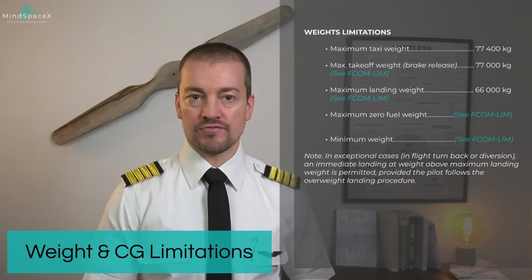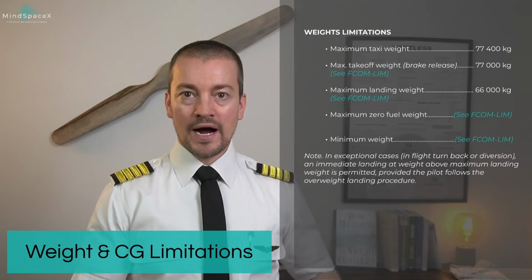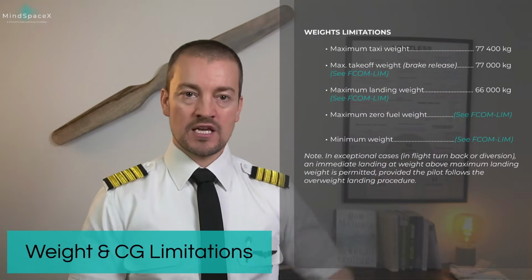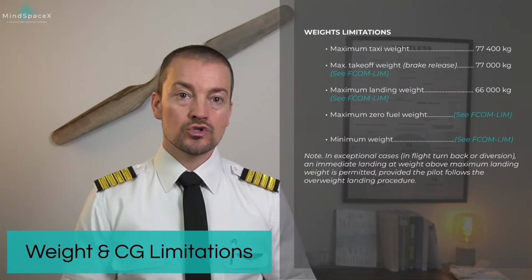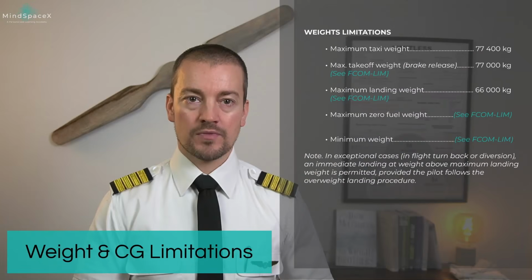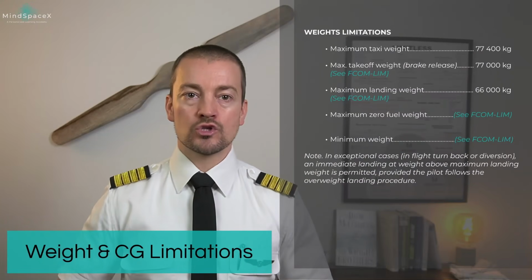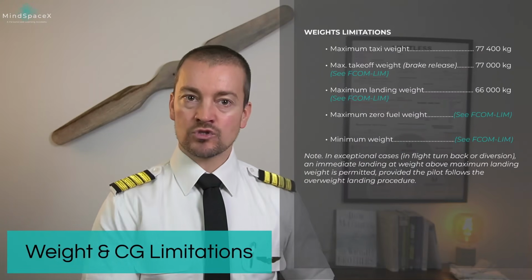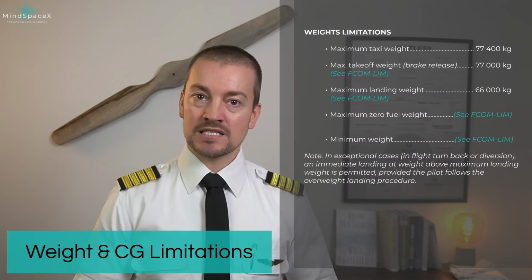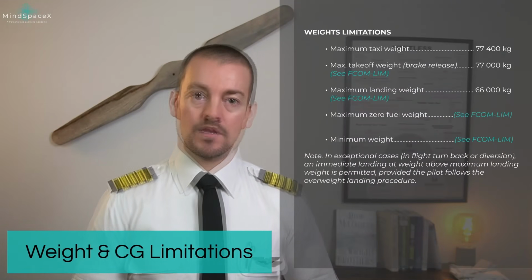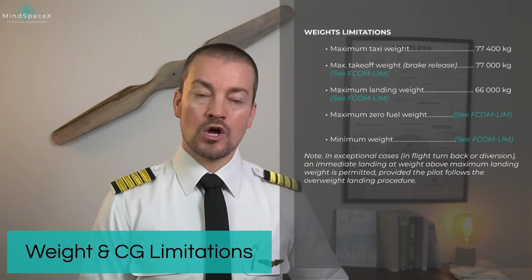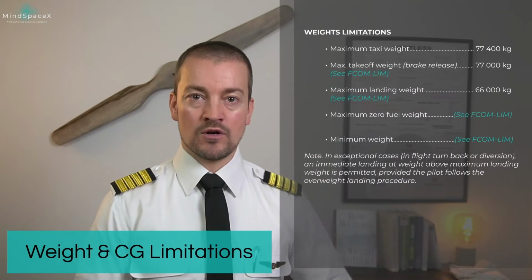intent to take off. So why do we have a slightly higher weight for ramp and taxi than we do for takeoff? Well, this is to ensure that we can carry the maximum amount of payload. We're going to be consuming fuel taxiing out to our takeoff position. And if we were already at maximum takeoff weight on the ramp, we would then be using that weight for fuel which we're going to burn on the ground, which could have been used for payload.